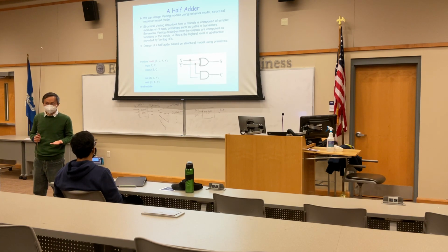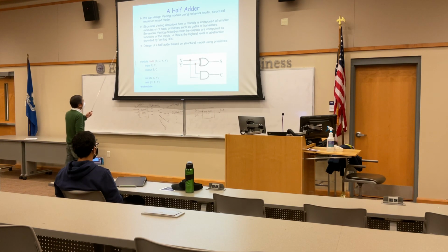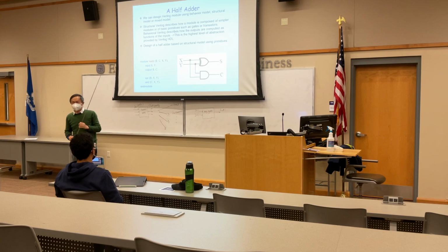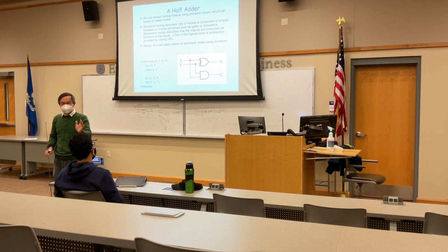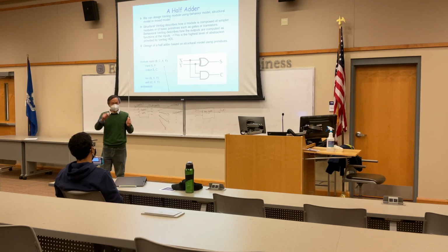You have flexibility. In logic synthesis, different synthesis tools may come up with different designs, but both of them get the job done. So a behavior model is a higher abstract level than a structural model. This is just like I assign you a task: you are going to finish it in 10 days, and how you are going to finish it, I don't care. That's a behavior. I just need to get the job done.